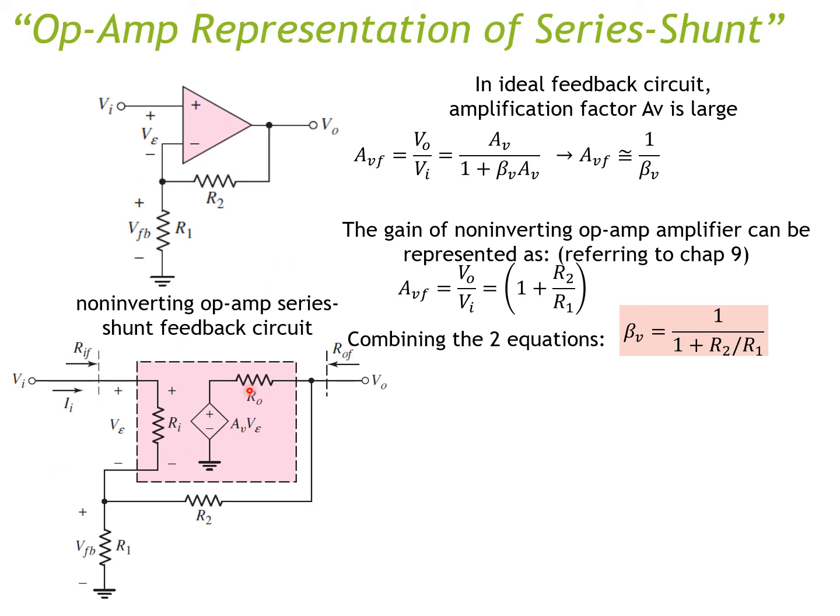Now I can have the small signal equivalent of this op-amp, like this. I have an input resistance and an output resistance from the op-amp. I know the gain of the op-amp. I can define my error signal and everything.